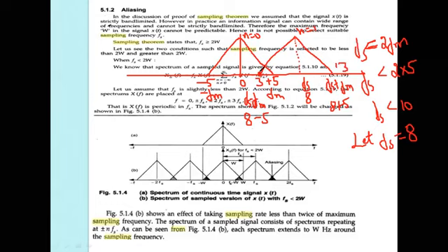Following, my students, now there is an overlapping occurring here. That means the high frequency content shows up in the low frequency region, and the low frequency content is inside the high frequency. Here omega is what I assume as Fm, and this one is Fs minus Fm, and this value is Fs plus Fm. And so on, 2Fs and 3Fs, when n is equal to 2 and n is equal to 3, that becomes X of F minus n into Fs.